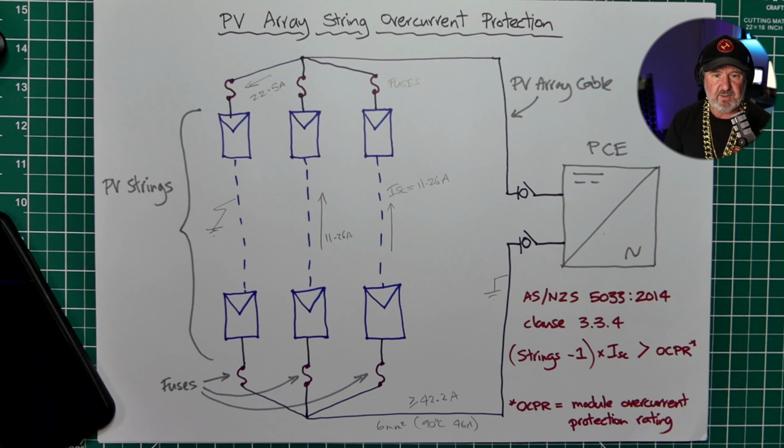Okay, so sorry, Nick's asking what table number do you use for 3008 for PV array cables? Well, it does depend on what temperature rating, because some PV array cables are 90 degrees, some are 120 degrees. I know the Radox cable we have here at the lab is 120 degrees, so that will determine what table. But I was using table 5 just then, which was for 90 degree 2-core, and I was using column 16, which is for enclosed in air against a surface. Yeah, so basically in conduit, and using flexible conductors. So that's where it came from. So thanks for that question, Nick.